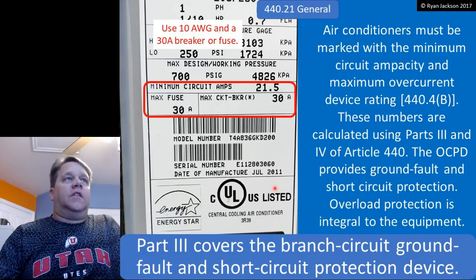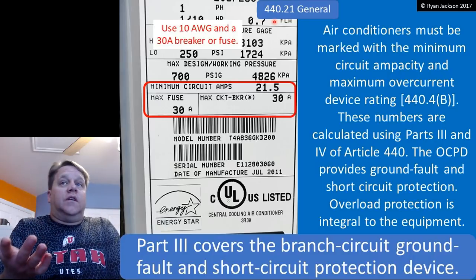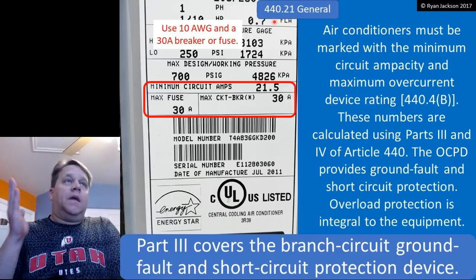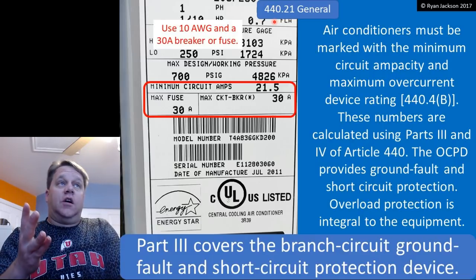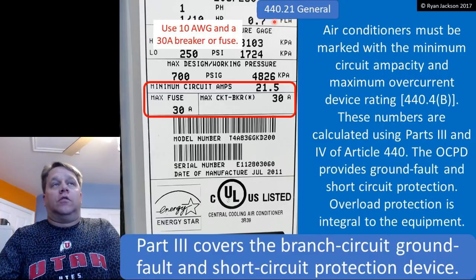Let's do one here, for example. This is 440.21, but in all honesty, you don't even need to read this in the code. All you need to read in the code is 440.4(B) and know that the manufacturer has done it all, and then you just go off the nameplate. You really don't need to read anything else in Article 440.